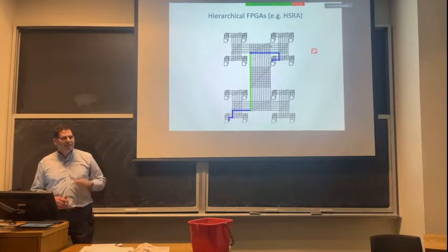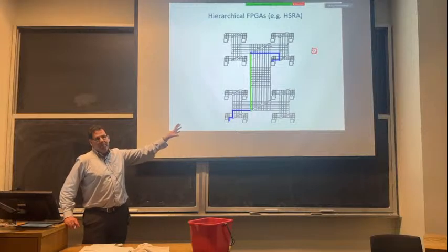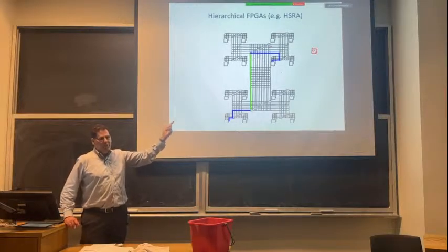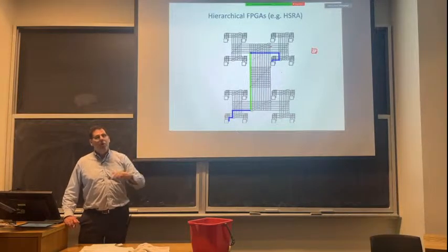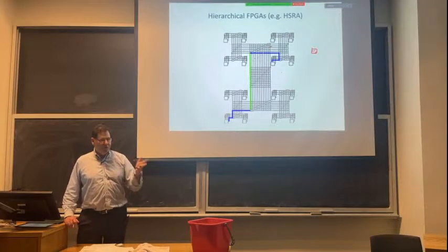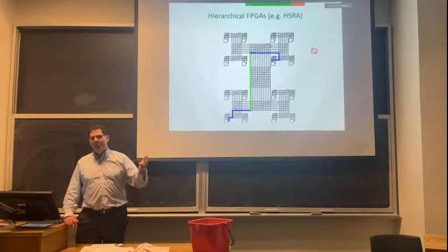Yeah, these wires have parasitics, so they have resistance, they have capacitance, which means you cannot assume these are zero delay at all. Nowadays, wiring is actually more important typically to delay than the actual transistors. The transistors matter too because they're driving the wires, but basically the wires are the big problem for speed.